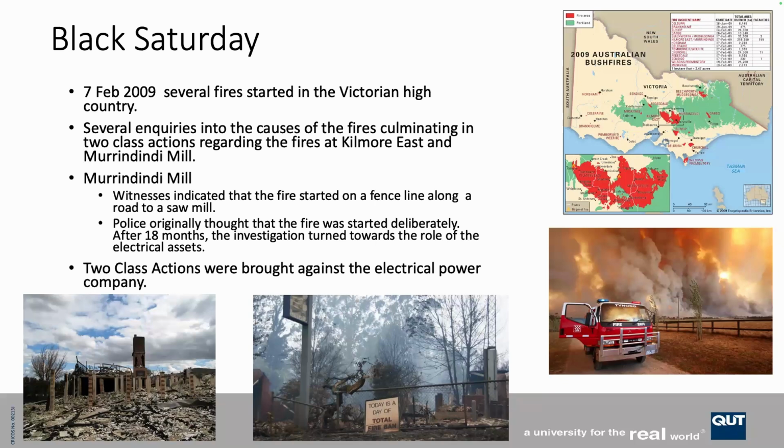The first failure appeared to be related to fatigue of a power line. It was a single steel wire power line that went to a single property. It spanned about 2 kilometers, and we think it might have got struck by lightning, which then started some fatigue cracks, and the thing failed. It's very difficult to inspect it, and it probably hadn't been inspected for a very long time. It was about 30 years old.